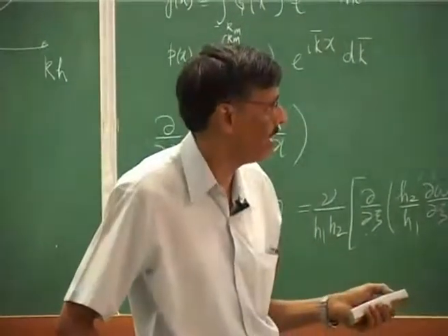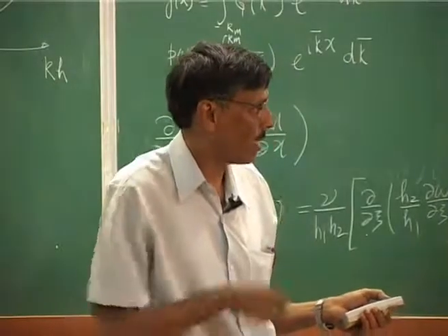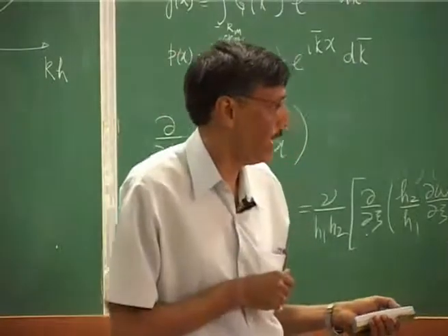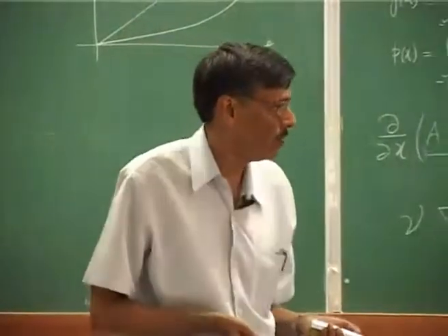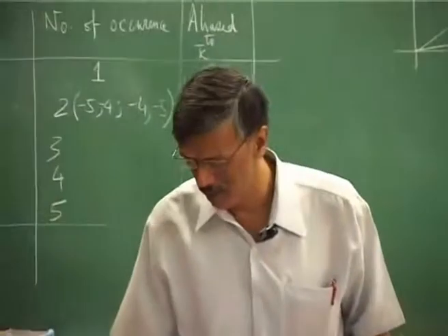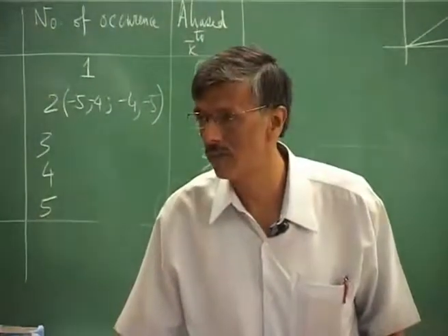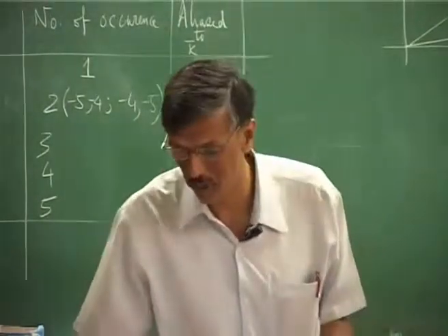So, we learned what is aliasing. We are now making an observation that higher order upwinding actually helps controlling aliasing error. Okay. So, if they are so for explicit schemes, they ought to be so for compact schemes, which are implicit schemes. That is what we note down there.